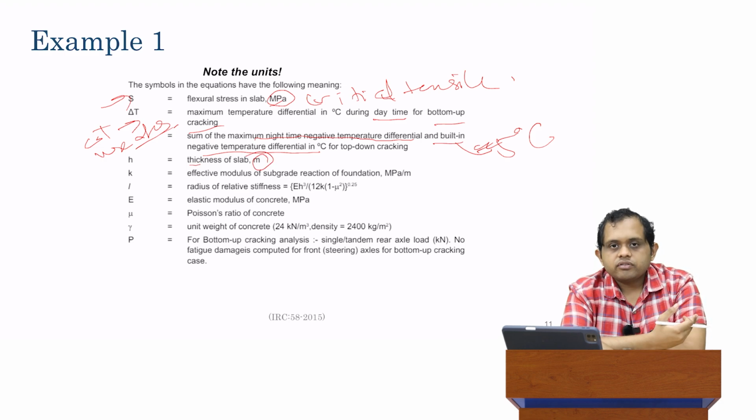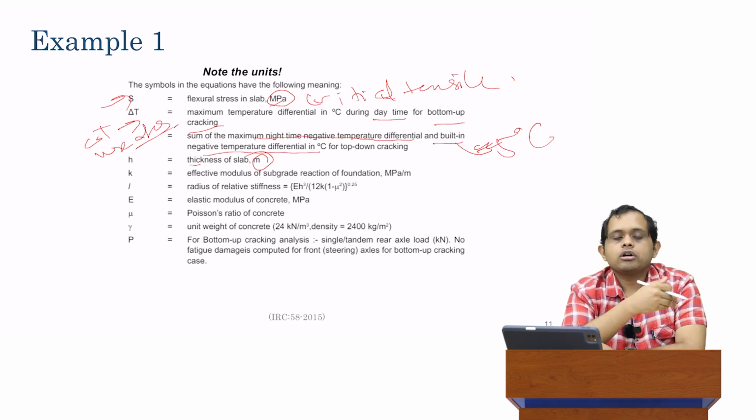As I mentioned previously, and it's a very important point, that's why I'm belaboring it a little bit longer. H generally in our regular conversation in a DPR, in practice in civil engineering, thicknesses, whether in slabs, structural engineering, or geotechnical engineering, thicknesses of structural elements or members are always shown in millimeters. That's just what our practice is. The regression equations, however, have been developed using meters.